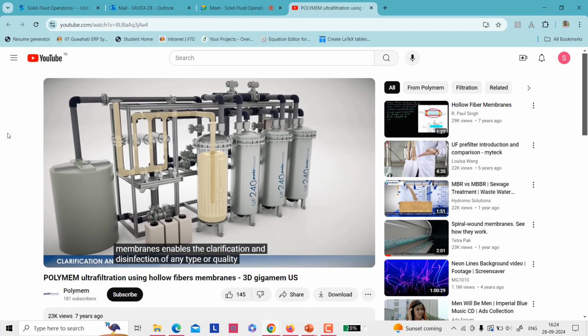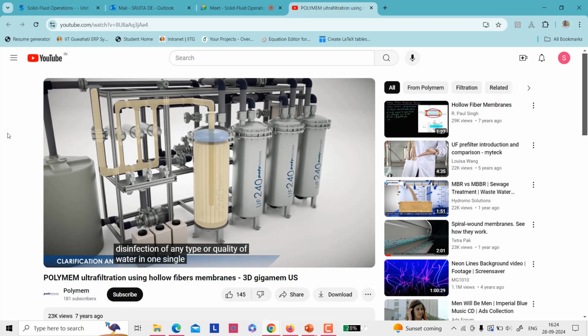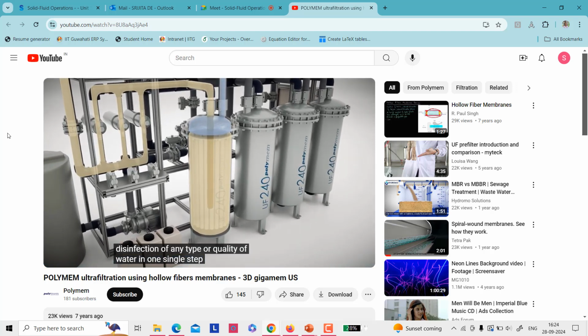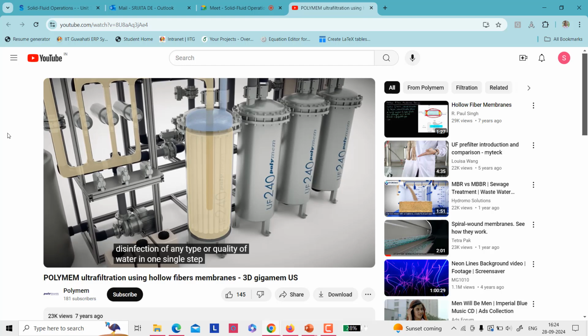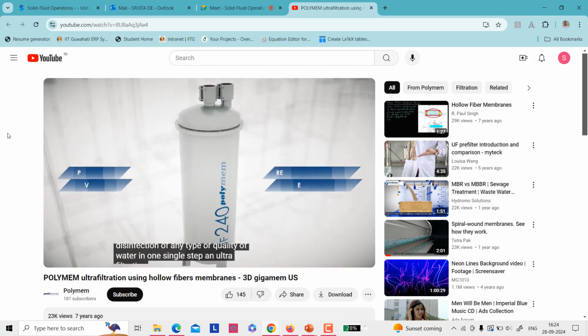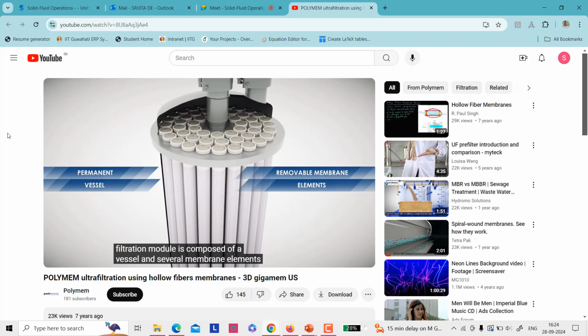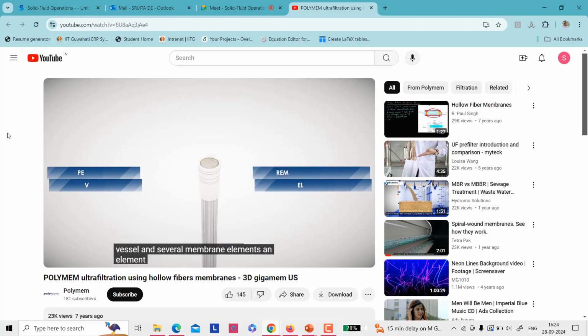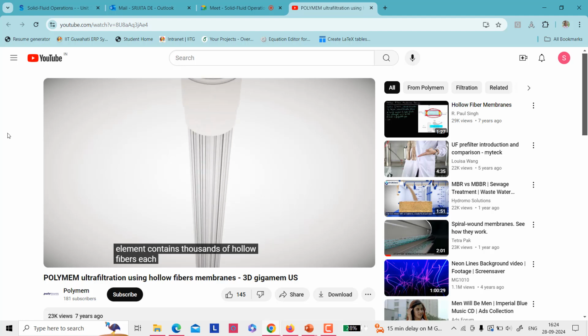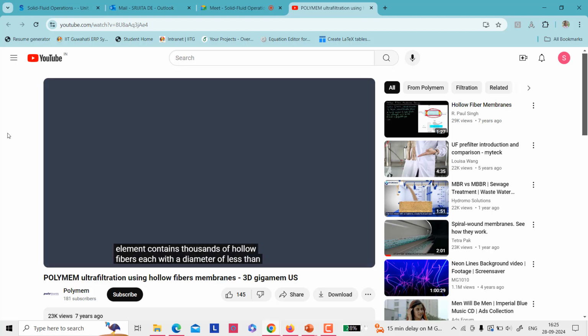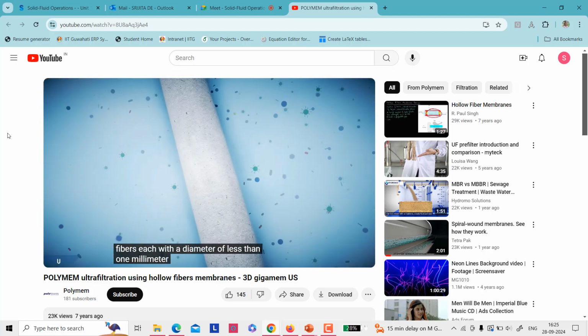This is the barrier against suspended solids and microorganisms including bacteria and viruses. The high filtration capacity and stability of the fiber are the result of the fouling resistant hydraulic polymers of which it is composed. Filtration is carried out in an outside-in dead-end mode.